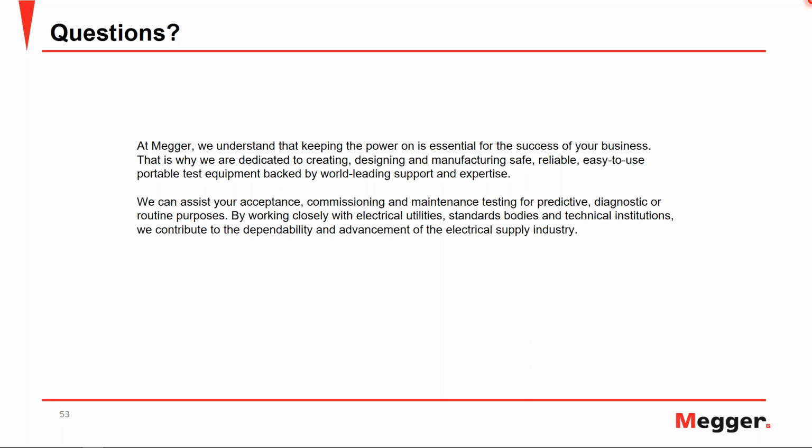I will give you an example. If I have a dry type transformer and I have a number of those dry type transformers available from the same manufacturer, then it makes sense to do a power factor measurement, because then I can do some comparative study and come up with some benchmark values. We also need to consider that when you talk about dry type transformers, the values can vary drastically.